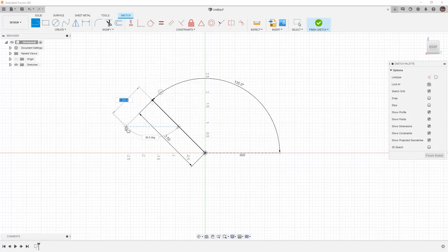Notice again that it's snapping to certain orientations. It's placing a perpendicular constraint in that corner. Because we want to learn and understand how to place dimensions and constraints, I'm going to begin just creating lines by dragging these over, and I'm going to avoid snapping to locations where we actually have constraints. and we'll work our way back to the origin point. As soon as we do, it automatically creates a blue shaded region inside of my closed profile. Notice that I'm still on the line tool, so I'm going to hit escape on the keyboard to get off of my line tool.